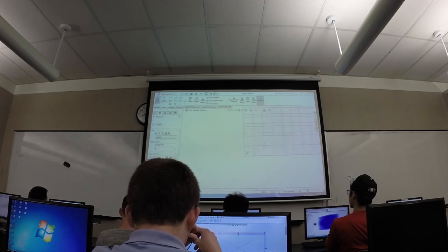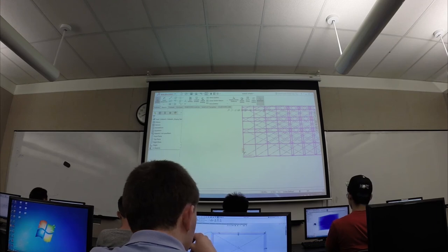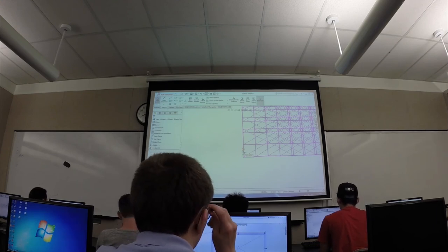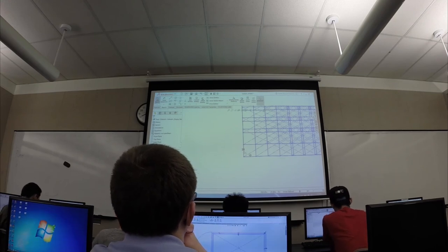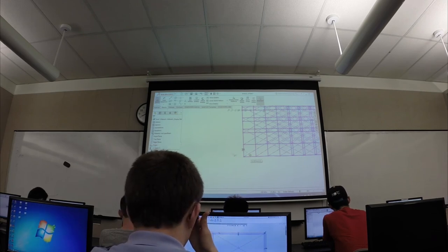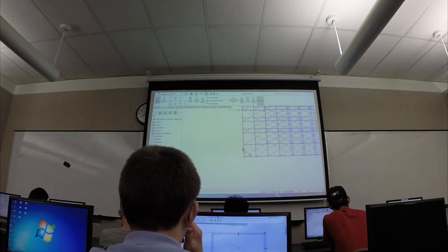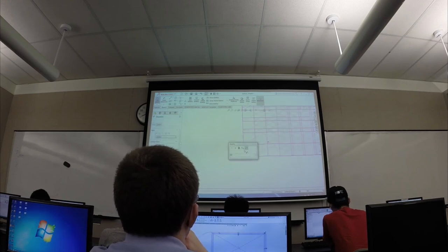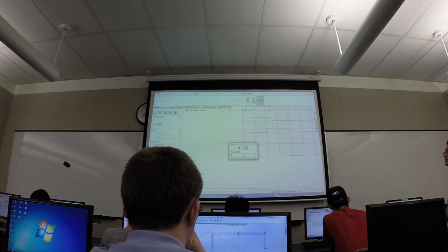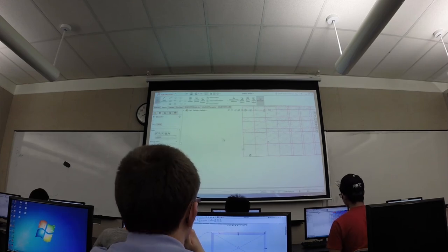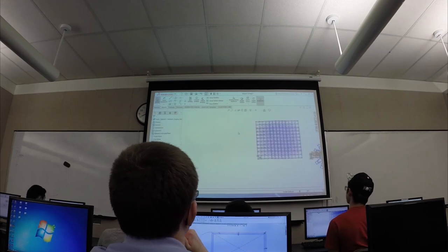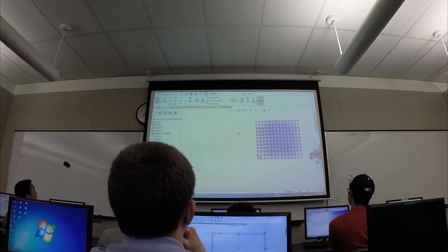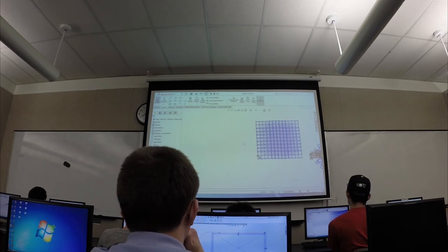So when you select that value, there's a value that floats there from the original shape that you started doing the patterns on. There are these little numbers. So this shows, okay, I did this 10 times, and then for the y direction, I did this 20 times. So it has those as definitions. If you were to edit that, let's say 10, we change that value to 10, right? The amount of instances that we just made reduces by what you set it to.